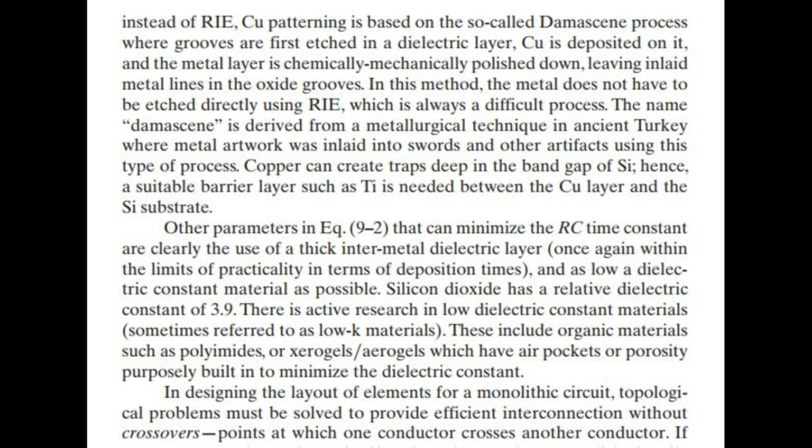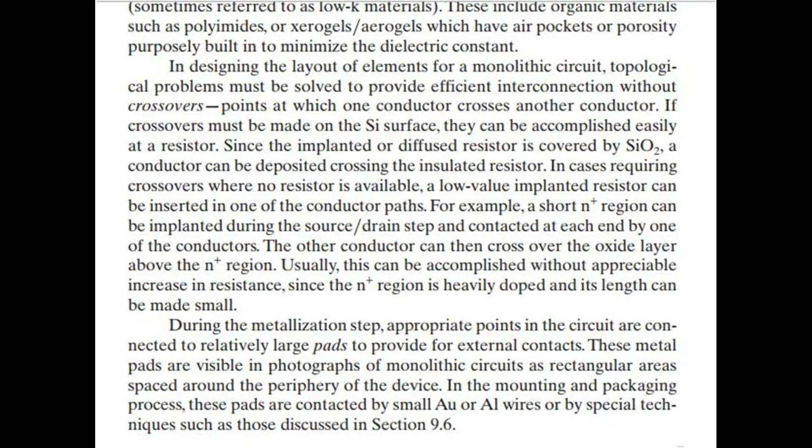There is active research in low dielectric constant materials, sometimes referred to as low-K materials. These include organic materials such as polyamides, or aerogels which have air pockets or porosity purposely built in to minimize the dielectric constant. In designing the layout of elements for a monolithic circuit, topological problems must be solved to provide efficient interconnection without crossovers, points at which one conductor crosses another conductor.